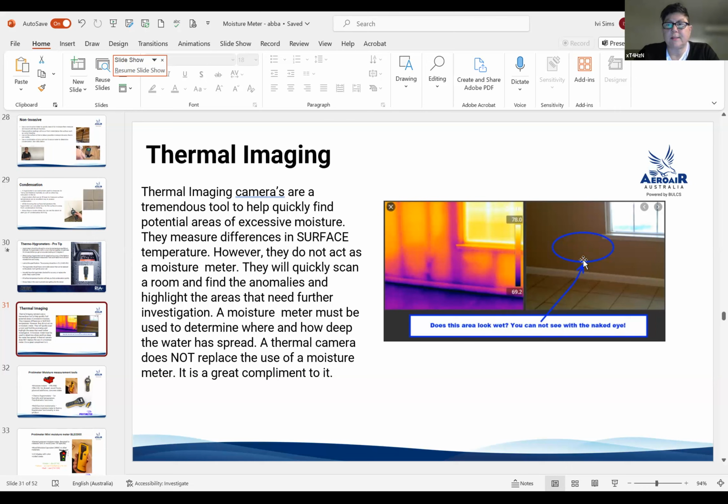The other thing that you might understand is ghosting. If you go into a place, somewhere generally around kitchen, barbecue areas, you would see black marks within a stud wall or the stud following the joist plates. And you're like going, why is that? That is mold, hey? Sometimes it's just that the thermal differences between the material has given the possibility of the carbon particulates to actually attract itself to the surfacing, creating darker spots within those areas.